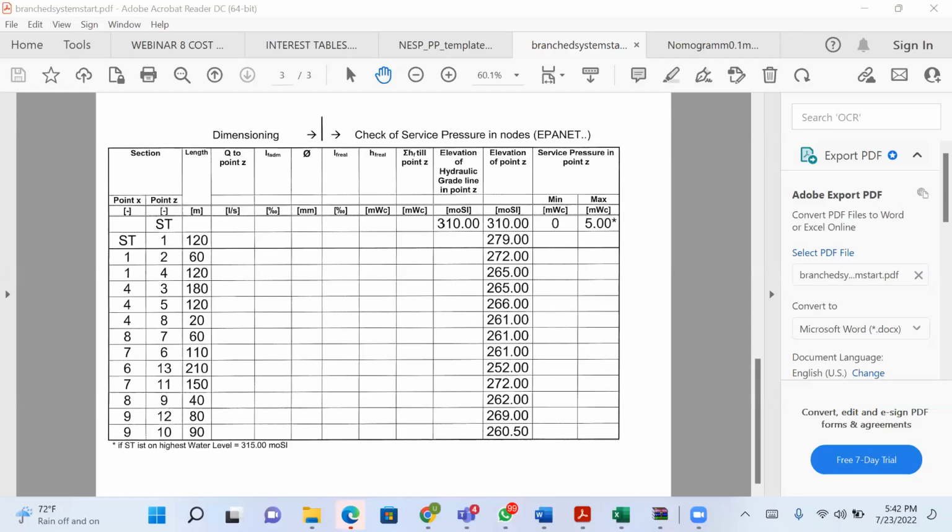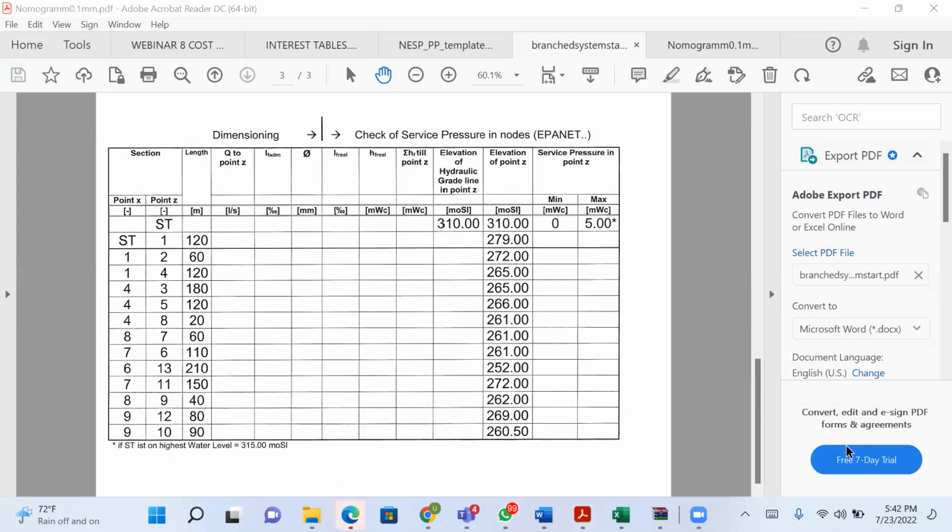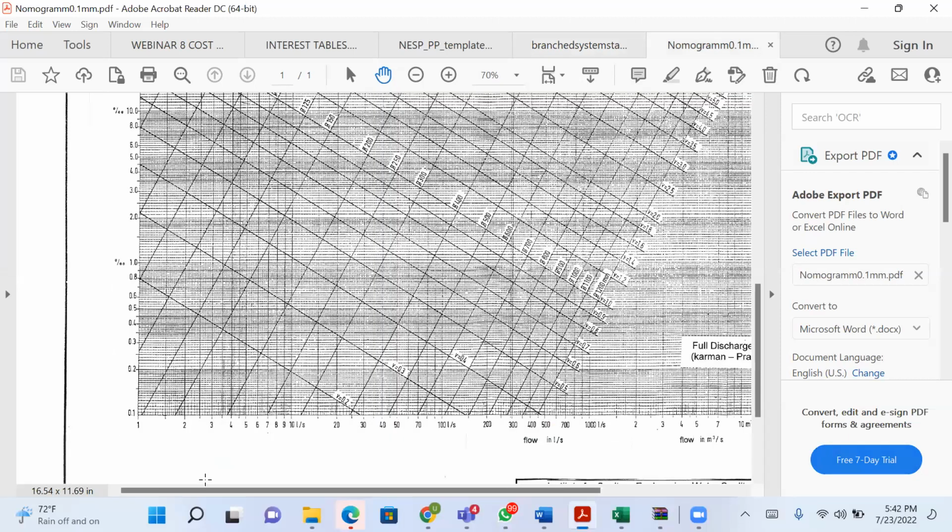Okay, so now I've gotten the slope as 0.4, right? And the water demand is 0.58. Because it's less than 1, I'll use the value for 1. And the slope will be what? 0.4. So that will be 100 mm.